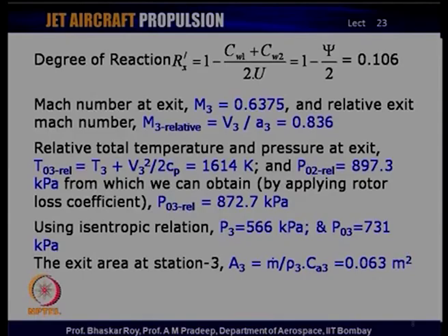Using the isentropic relation, we can now find the stator static values, that is P3 as 566 kilopascals, and the total pressure is 731 kilopascals.